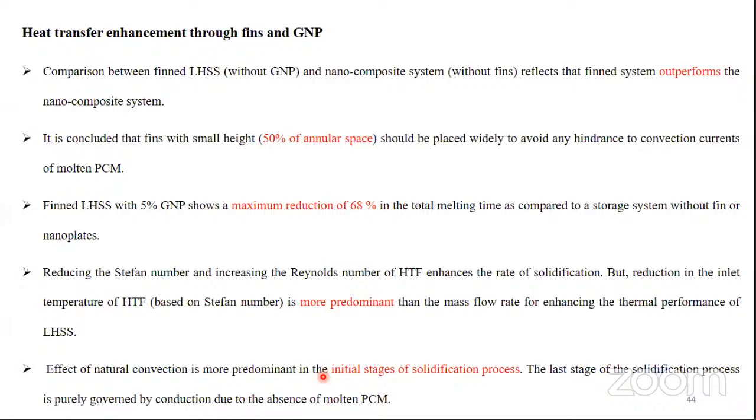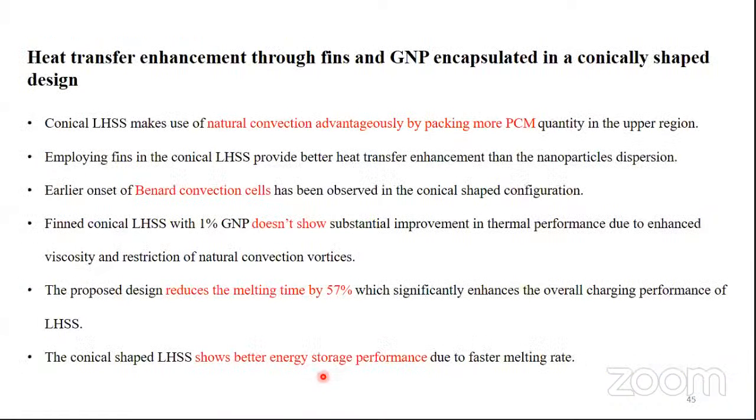Now coming to the effect of natural convection, of course, the effect of natural convection is more predominant in the initial stages of solidification. And when we are going to the last stages of solidification, it is purely governed by conduction. And as I told, when we are having the fins, they can actually act as the heat source. So that is also one of the important conclusions. So for heat transfer enhancement, the conically shaped thermal energy storage system makes efficient utilization of the natural convection advantageously by packing more PCM quantity inside the upper region.